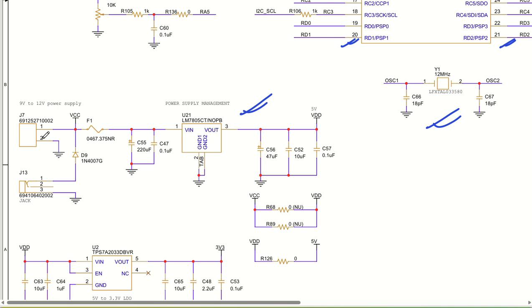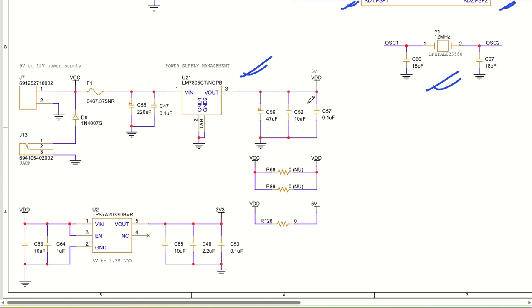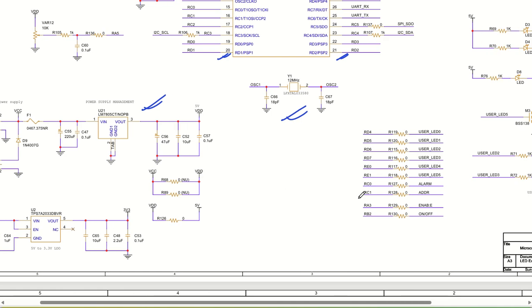So what will happen is, let us say the voltage at this point is more, then this particular voltage will be used. If the voltage at this point is more, then this will be used. Okay, so this is how it will be working. Anyway, it is always recommended to put only one of them, not both, so you avoid putting both power supplies together. In many places you will see that VDD has been used as 5 volt, but for better purpose sometimes I use the net name 5V. So I have used one resistor, so this VDD can be supplied through this resistor and the net name changes to 5 volt. So 5 volt will be utilized everywhere.